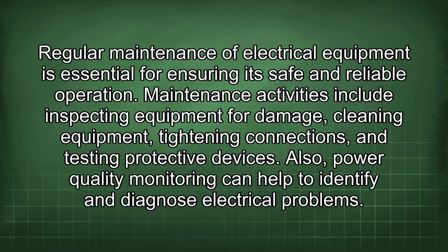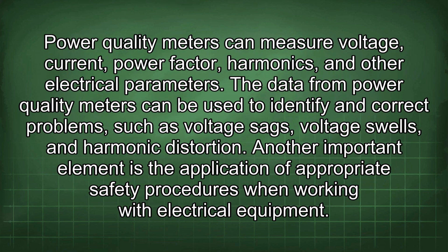Also, power quality monitoring can help to identify and diagnose electrical problems. Power quality meters can measure voltage, current, power factor, harmonics, and other electrical parameters. The data from power quality meters can be used to identify and correct problems such as voltage sags, voltage swells, and harmonic distortion.